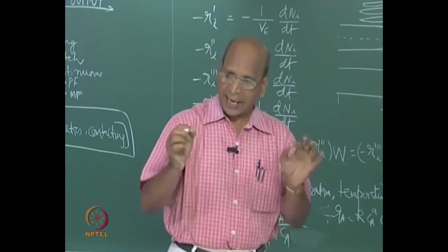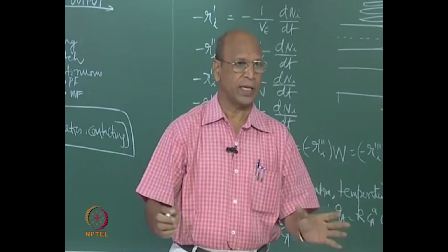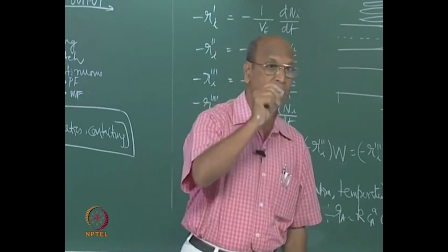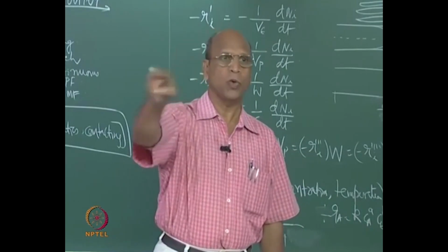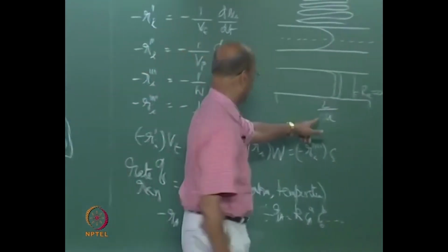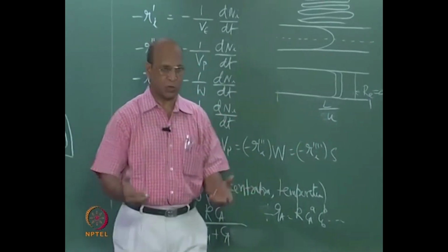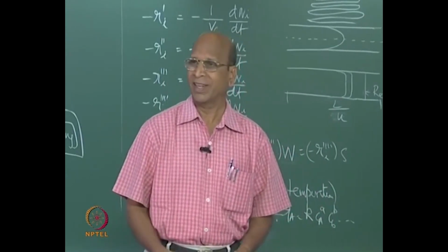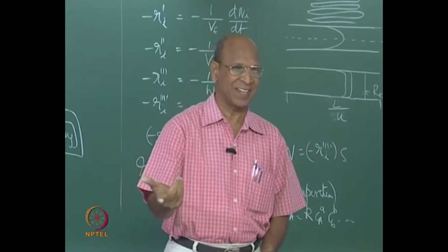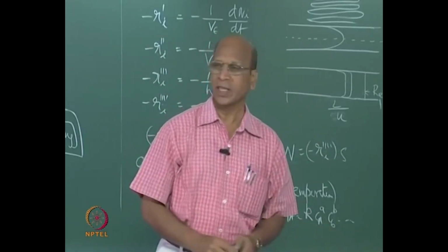Okay. So, the ideal plug flow is only existing when you have velocity equal to infinity. That means you cannot provide even 0 second, correct? Tau equals L by U, this U equal to infinity, then it becomes 0, and with 0 time, if some reaction is happening, you do not need any reactor at all. You simply do not need any reactor, because even before you mix them, if they are reacting, why do you need a reactor? You do not need anything there.